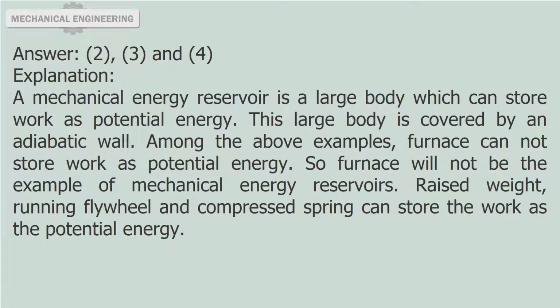Answer: 2, 3 and 4. Explanation: a mechanical energy reservoir is a large body which can store work as potential energy. This large body is covered by an adiabatic wall. Among the above examples, furnace cannot store work as potential energy. So furnace will not be the example of mechanical energy reservoirs. Raised weight, running flywheel and compressed spring can store the work as the potential energy.